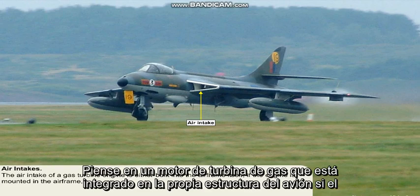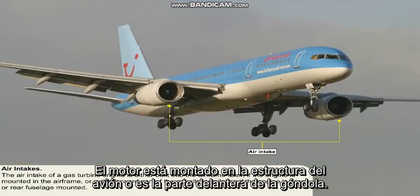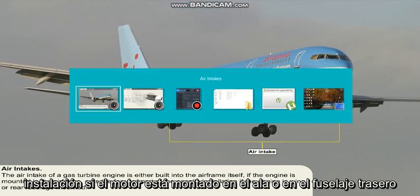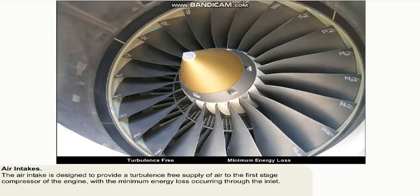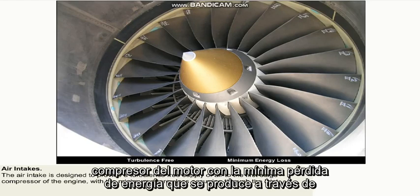of a gas turbine engine is either built into the airframe itself, if the engine is mounted in the airframe, or is the forward part of the nacelle installation if the engine is wing or rear fuselage mounted. The air intake is designed to provide a turbulence-free supply of air to the first stage compressor of the engine, with the minimum energy loss occurring through the inlet.